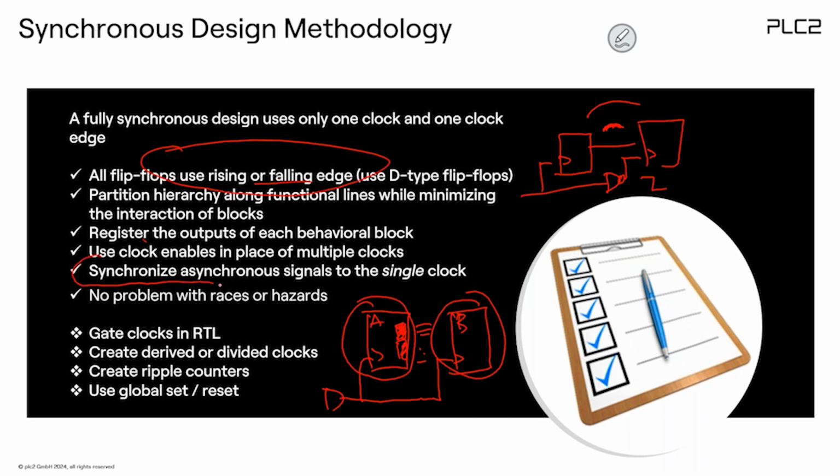Also, very important, synchronize. We'll also talk in this webinar about this. Synchronize asynchronous signals to a signal clock. This means if you don't synchronize this, you will have an asynchronous design, because you will use this asynchronous signal maybe to do something. No, you should synchronize this.